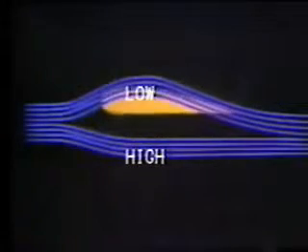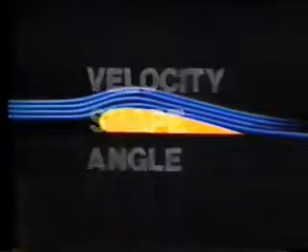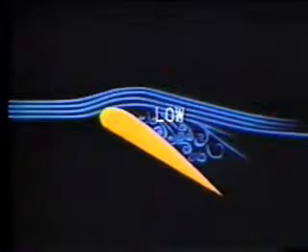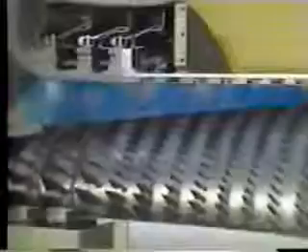Let's use the airfoil to explain low-speed stall. The airfoil is designed to affect airflow to form a pressure differential across the foil which creates lift. There are three factors which affect the performance of the airfoil: its velocity, its shape, and the angle the foil meets the air. If the angle the foil meets the air becomes too great, the low pressure area begins to draw air back down onto the foil. This turbulent air condition upsets the smooth flow of air and destroys the low pressure area, which causes a loss of lift. When this happens, stall has occurred.